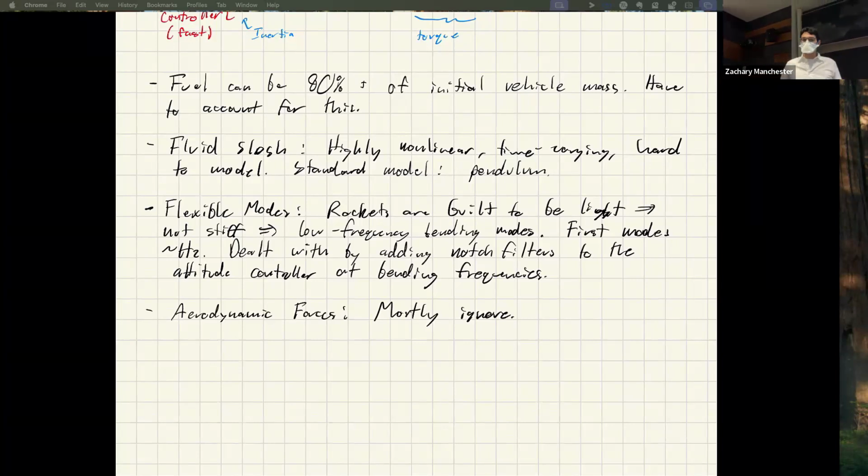And you can make sure that these are small by having velocity constraints in the position controller. So you don't want to be flying that fast. And remember that aerodynamic forces are proportional to velocity squared. So V small, V squared is really small. And then these things don't matter that much.